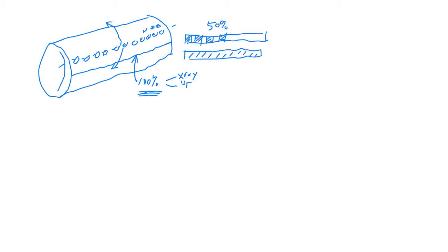By design, we want those holes to be there because we've got to attach the tube somewhere. And now the weakest part is this plane here, which we said is only, in this case, 50% efficient. In that case, E is going to be the lesser of this efficiency and that efficiency, so obviously 0.5. Okay? We good? Yep. All right.